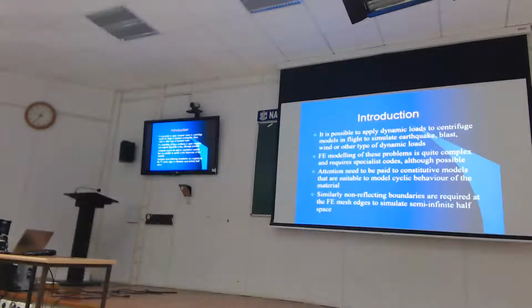Because of the way energy scales, that's something you can derive again as part of your newfound scaling laws. If you find the scaling law for energy, you will see that it scales as n cube, which means in a centrifuge we can have really small amounts of explosives, and you can model something that is much bigger, n cube times bigger. So at 100 g, it's 100 cube that is how energy scales. So it's a big advantage to model explosions in a centrifuge.